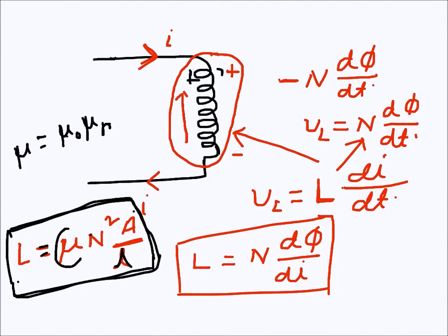And yeah, this is just the basic property of inductance. And we know in an inductive circuit the current cannot change instantly. So if we have something like this, let's say a switch there, so maybe the switch is closed now, and an inductance there. If suddenly the switch is opened, theoretically the current has to stop immediately, but an inductance will not allow that to happen. So what will happen,